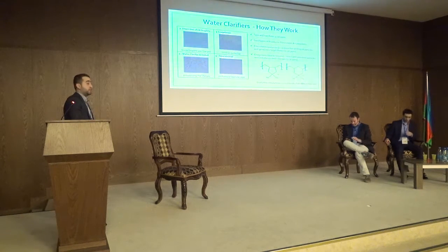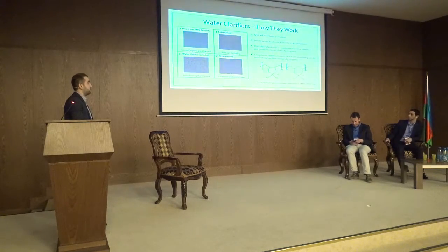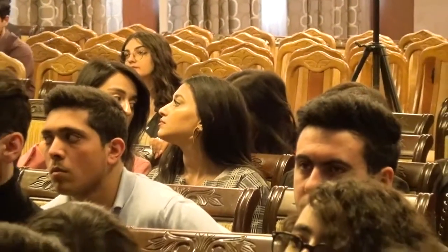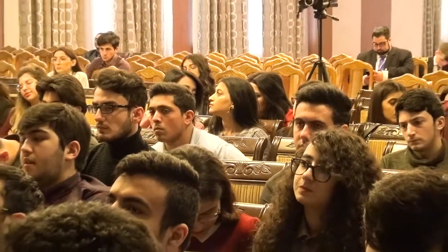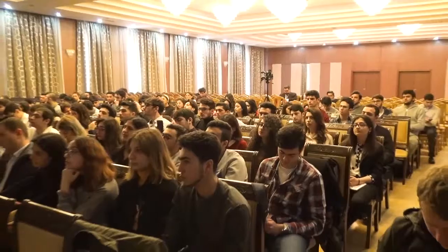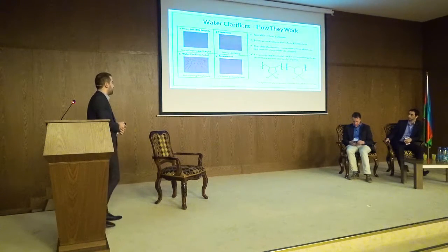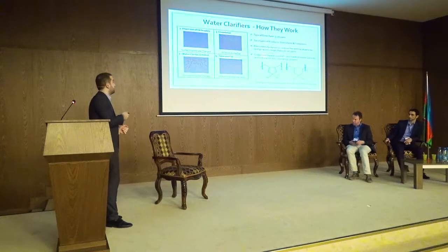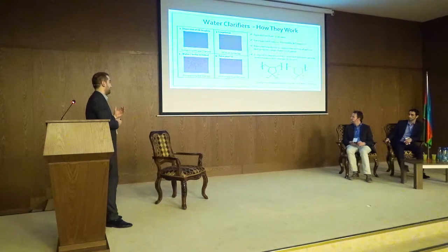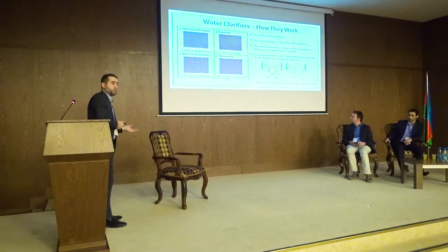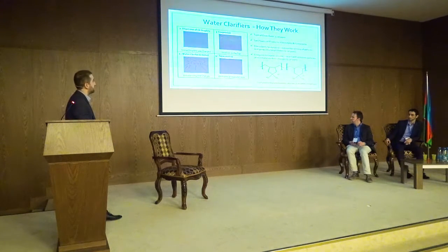And there are two types of water clarifiers. General classes are flocculants and coagulants. The flocculants are usually polymers, and they induce the settling particles and grow into larger flakes, like this. So this is actually a physical process. For the type of chemical, I just put an example here. This is a DADMAC polymer. We actually don't care about the chemical formulation, the chemical composition of this flocculant, because it's a physical process. You only need to coagulate floc to make bigger floc to make your separation efficient. So if the polymer is okay, you have to apply that chemical in that system, and get your separation.